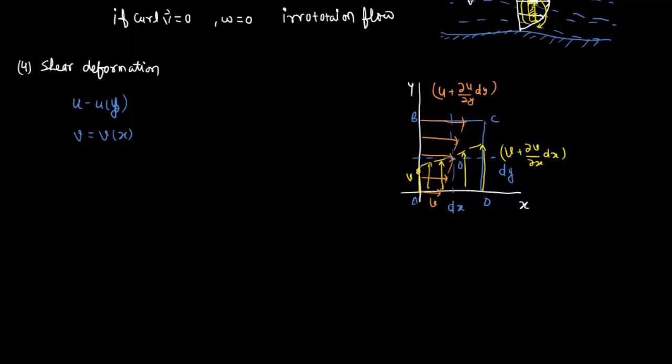So what are the velocity gradients in this case? We can check here and define this gradient, which is actually positive here, that is ∂v/∂x. This is a gradient and this is positive here. Positive here means this is in the positive y direction. Okay, and this is also positive over the face BC here. I'm not saying this is the value, I'm defining the gradient here. So the gradient here is also positive, that is ∂u/∂y, and this is also positive. Positive means this is in the positive x direction. So this is in the positive y direction, this is in the positive x direction.